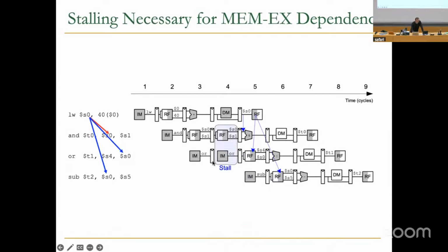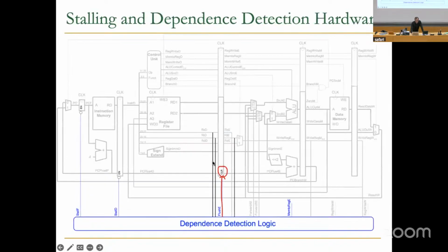This also needs to stall, of course, right? Okay. So in order to stall, you need to make sure later stages get inserted no-ops. So your book does it by clearing the pipeline register in the stage where the instruction is stalling. This instruction is stalling over here. It cannot move.